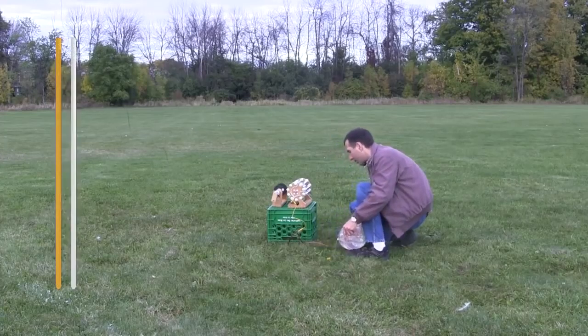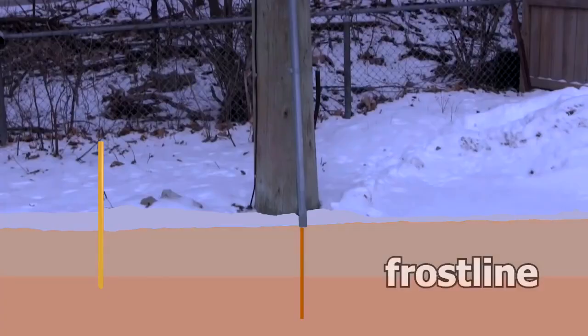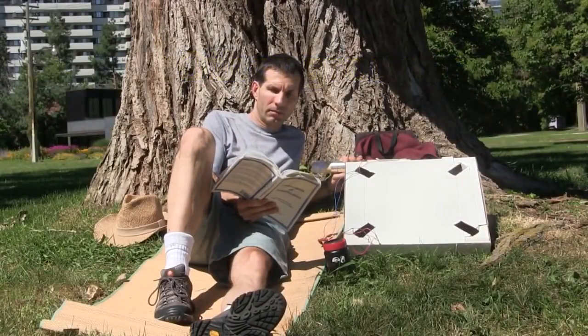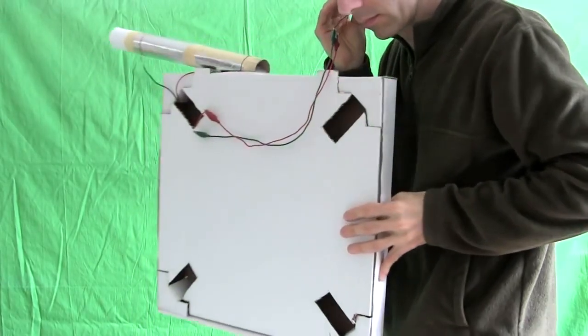You can buy copper and galvanized steel rods that are around 6 to 10 feet long, that you can pound into the ground. But keep in mind that cold ground lowers the conductivity, so make sure to drive it below the frost line for winter use. Besides the ground hole in a power socket, where can you find a ground to use? If the current and voltage aren't too high that you get hurt, then your own body can sometimes act as an okay ground. An example where I've done that is with this portable pizza box crystal radio.